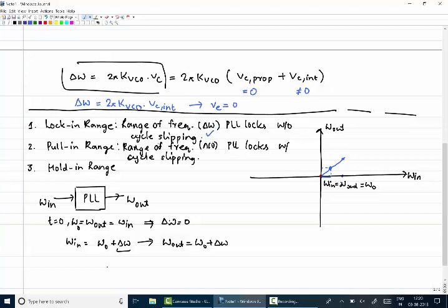Then I brought in the integrator and a proportional path, so that you can lock into these frequencies also, with F of 0 tending to infinity. Then I also showed you some examples where the frequency error was large, so it was cycle slipping also. That concept I introduced after introducing the integrator and the proportional path both.